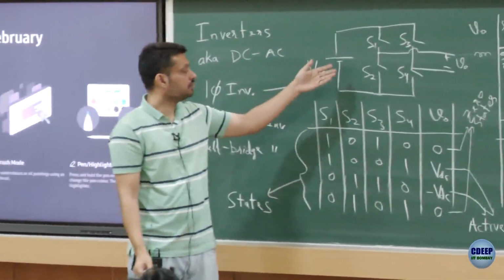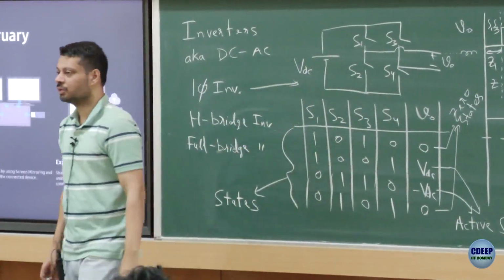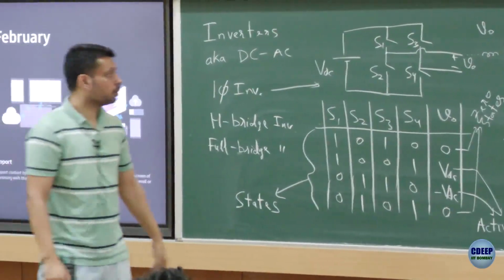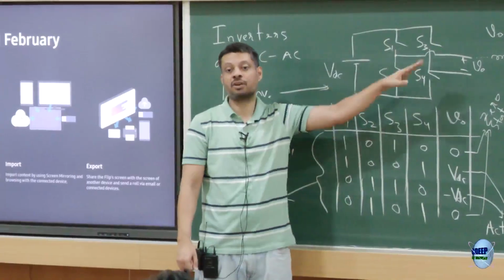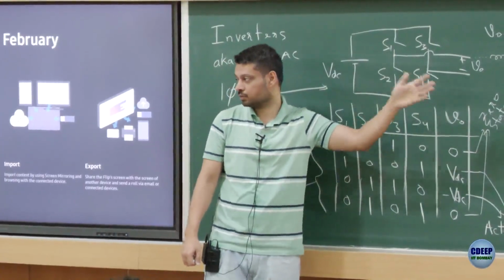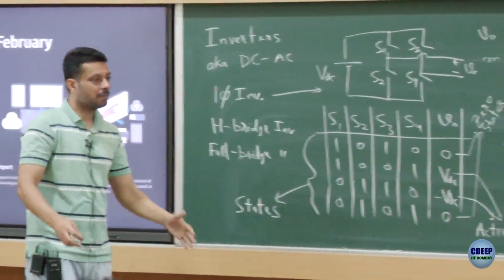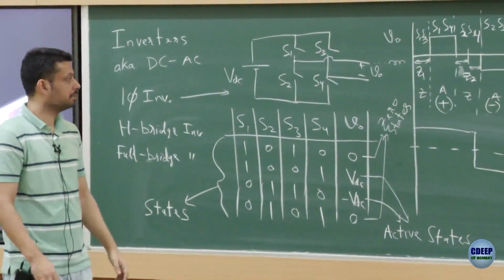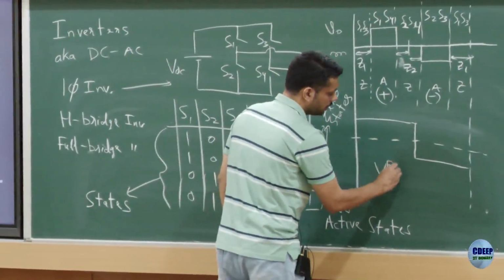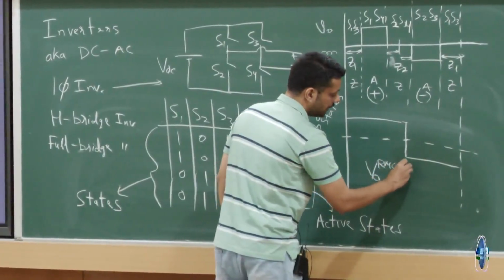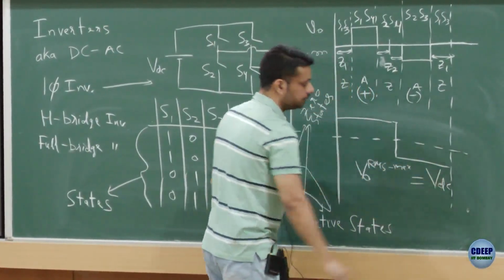Right? So, you can keep reducing the voltage. It's not, let's not call it a buck converter or something, but you get the idea: the output RMS voltage is limited by the supply DC voltage, and you can always produce smaller than that. You cannot produce more than that in this kind of circuit. So, yeah, it's not a buck converter, but you get the same sort of feel here, right? So, V output RMS max is equal to VDC.